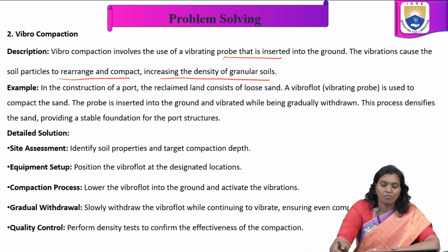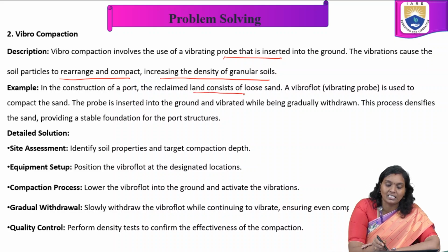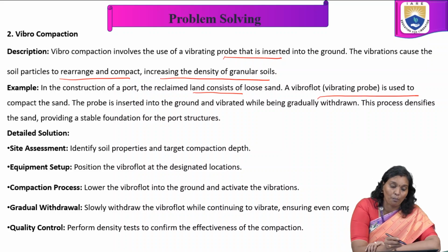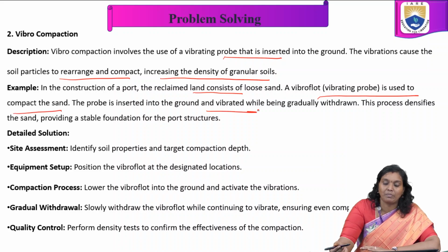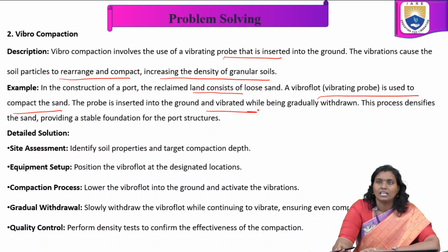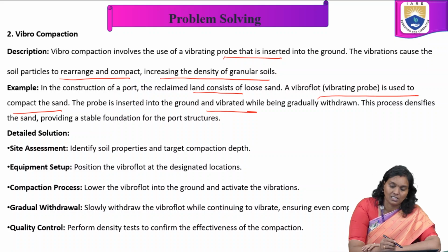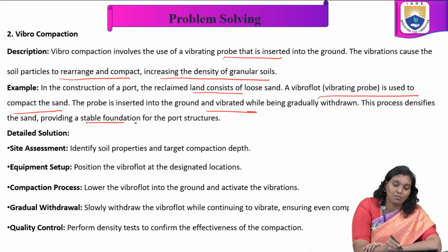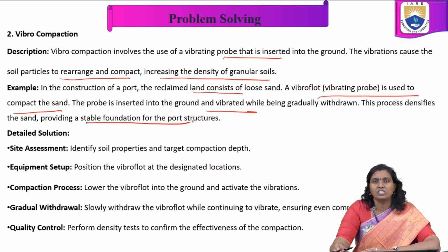In the construction of a port, the reclaimed land consists of loose sand. A vibro probe is used to compact the sand. The probe is inserted into the ground and vibrated while being gradually withdrawn. This process densifies the sand, providing a stable foundation for the port structures.